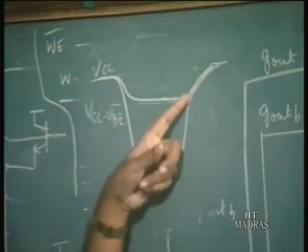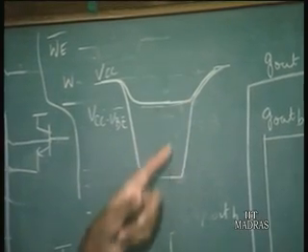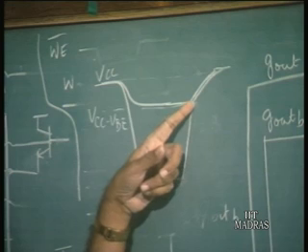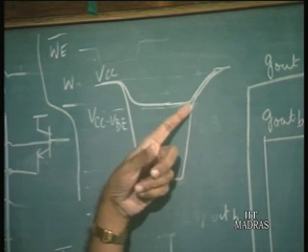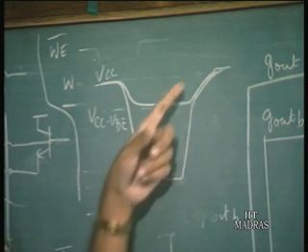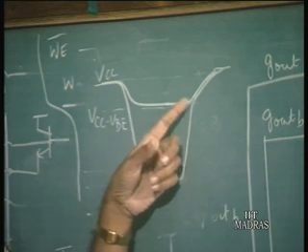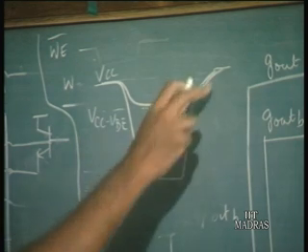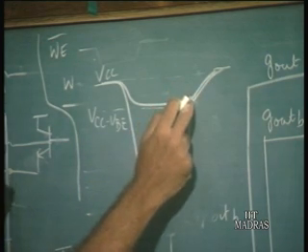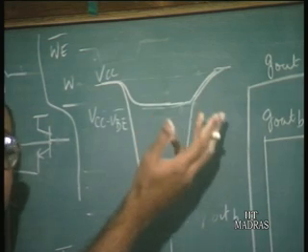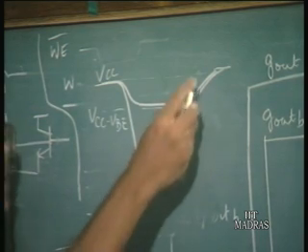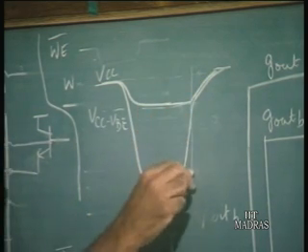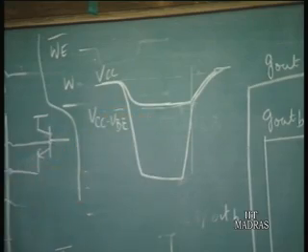So, once the voltage on this line goes to VCC minus VBE, both the lines are equalized, and although both are not equal to VCC, they are rising slowly, both the lines have equal voltage. So, it is ready for a read operation. It is ready for a read operation at this instant only. So, that is the reason why the other line is going to be pulled down.